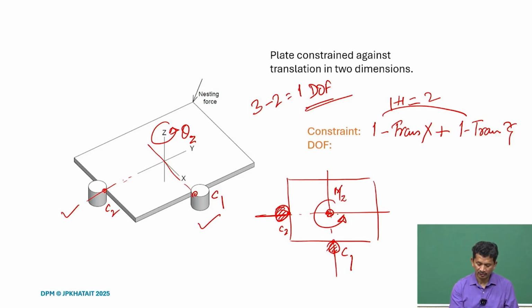What you realize is that the 2 constraint lines, if you extend them, intersect at a point, and if you try to rotate about that axis, what will happen? If you drop the perpendicular to the contact point, you realize that it can slide easily along that interface, at C1 and C2 both, because of the instantaneous motion if we try to apply a moment along the z direction.